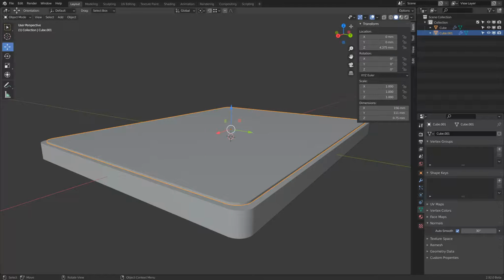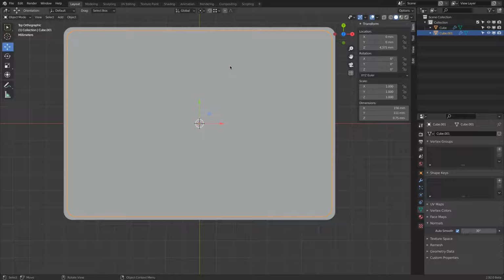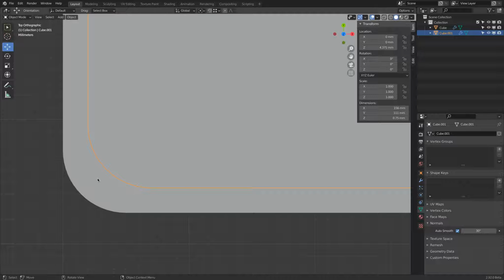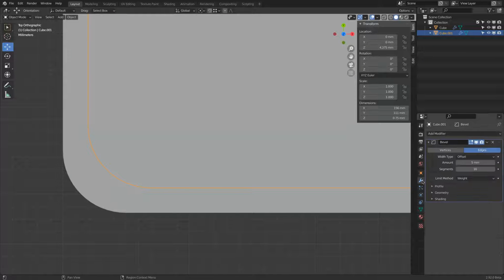Okay. Nearly done. We can take a look at the top. What is wrong? The distance or the offset is actually correct. The radius, however, is not. We zoom in there, we can see that it gets thicker. Why? Well, we moved the edges, but we kept the value for the bevel the same. We moved this by 2 millimeters in. That means 5 millimeter radius minus 2 millimeter material thickness difference, or offset, is 3 millimeters. You see with 2 or 1 it gets closer, or 0, so it will be 3. Okay, now there you see that actually looks better.